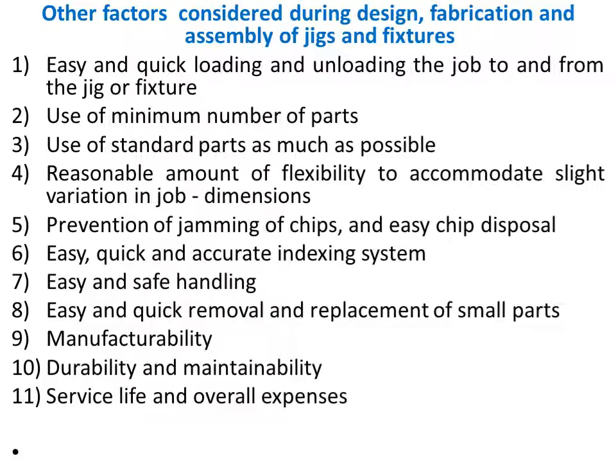Then easy and quick removal and replacement of small parts. Then manufacturability of the fixture should be very convenient. You have to use the kind of material, and the manufacturing should be done without much difficulty.